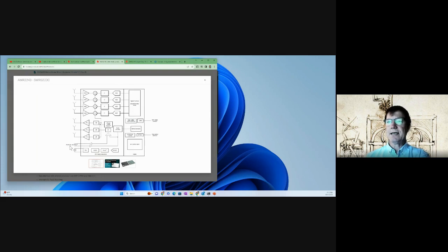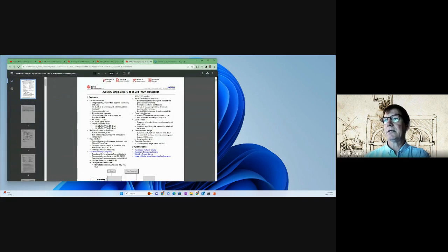This multi-chip cascading allows you, and they actually have that registered as a trademark, or is that just a note there? I can't read it. So this allows you to synchronize these ramps and the synthesizers across chips. So you're using one ramp, one chirp for all of them, right? So if you're cascading these chips, then you're going to use one of these synthesizers, and it's going to drive all your other chips.